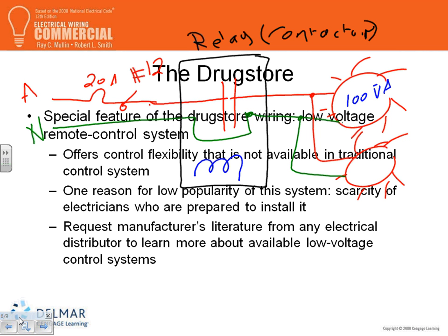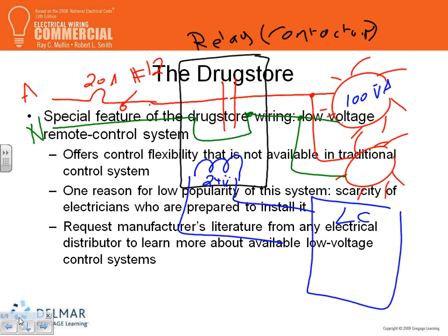It's a contactor that opens and closes, and a relay that physically, mechanically drives this contactor by magnetic force to close and open it. So here's the contactor. You land the hot in one side and you pull it from the other side. That's a contactor. The relay, the coil, is a 24 volt coil. This is a 24 volt coil. And you bring this, in our case, to a lighting control panel, and you power it from a lighting control panel. And you put a tiny little switch in it here, and you bring two conductors to a lighting control panel relay.